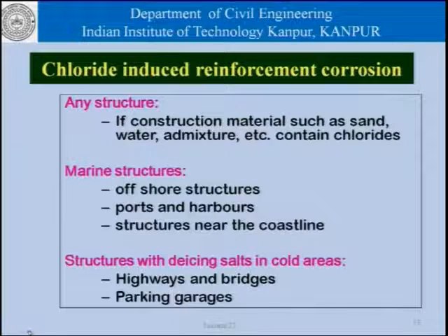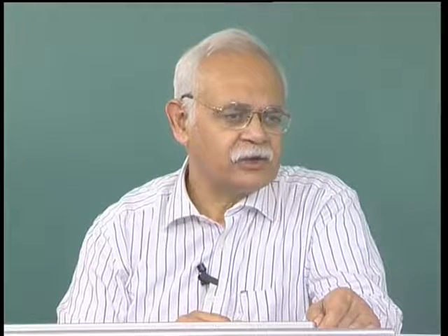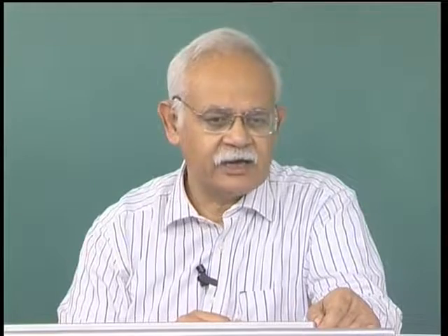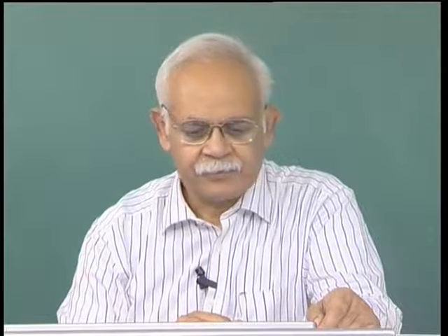So, getting started, let us recall that chloride induced reinforcement corrosion can occur in any structure if the construction material such as sand, water or admixture contain chlorides, and that is why our codes and standards lay down specific limits on the maximum permissible chloride content in sand, water, admixture, and so on.